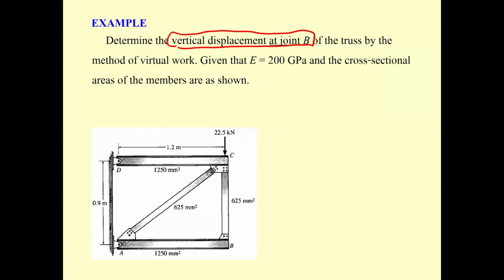You have the truss, right? So this is V sub dx equal to V sub dy equal to 0, V sub ax equal to V sub ay equal to 0. No movement. Following this concept, you can see this one and this one are going to be zero force members. When there is a zero force member, there is no deformation.